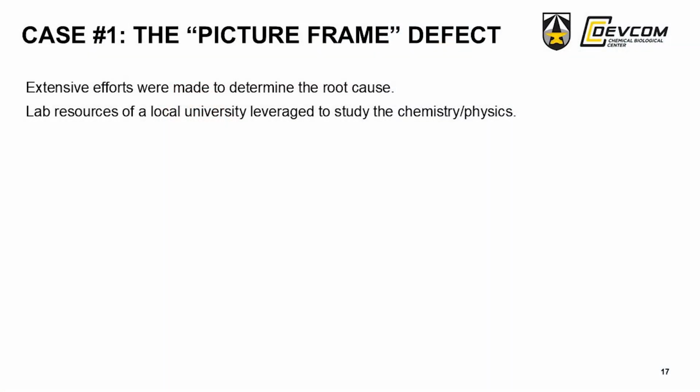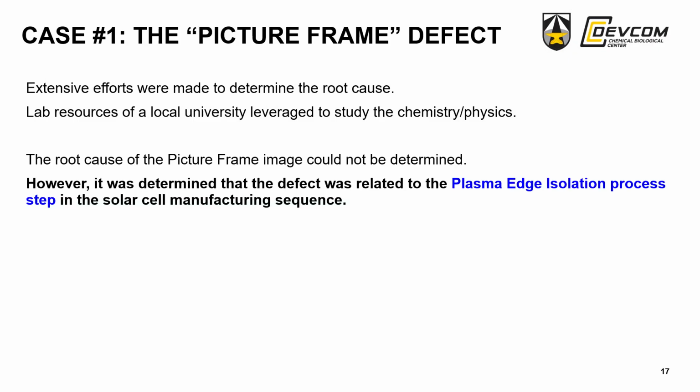We made extensive efforts to try to get to root cause. We took a very scientific approach and brought in a local university. They're studying with SMEs, EDAX. They're looking at the molecular level to try to find out what is causing that ring. Never did get to the root cause of it, but we determined that it is associated with this plasma edge isolation process step that was in the manufacturing line.